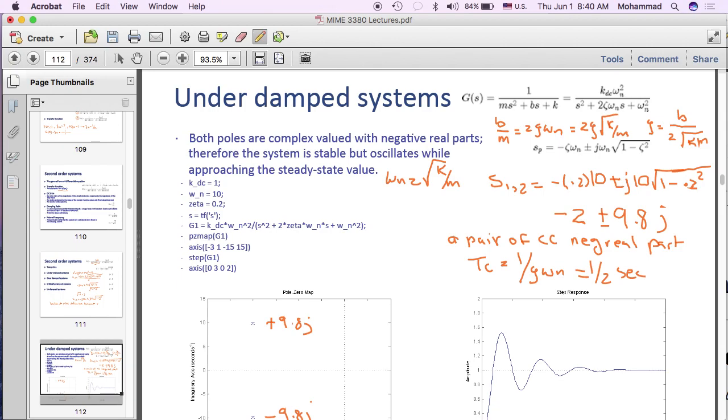So the bottom line is you don't know what the steady state response is unless I gave you a third piece of information, either giving you m or giving you stiffness or giving you b, the value of damping. If you have that third piece, then you can plug it into these two equations and figure out what k is. So we don't know what k is.